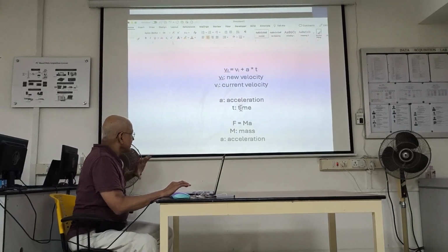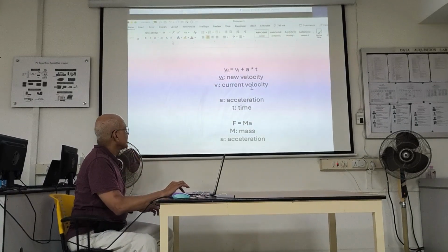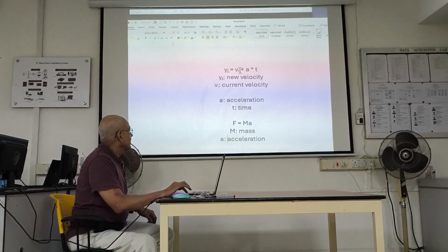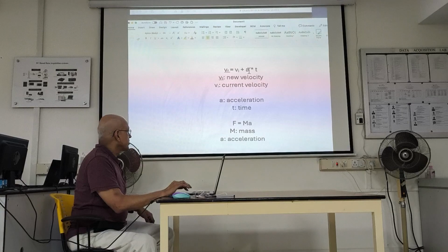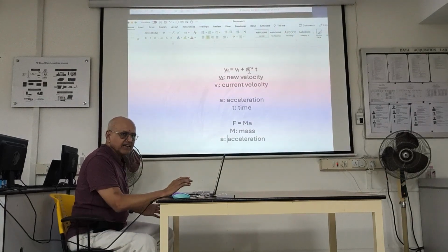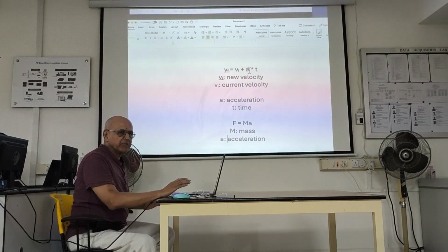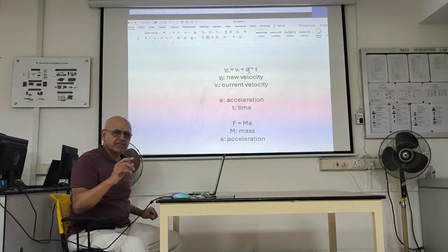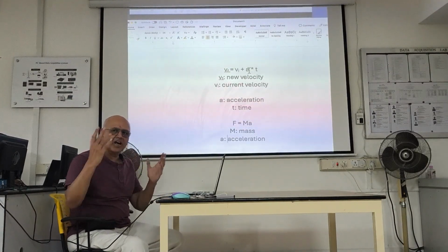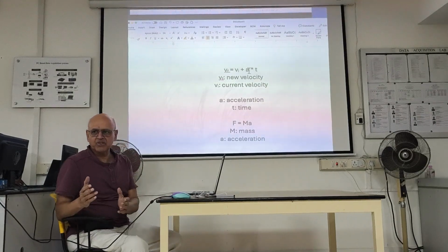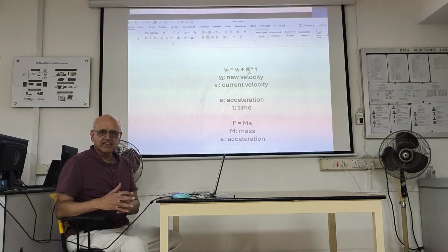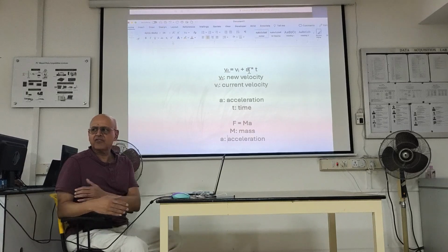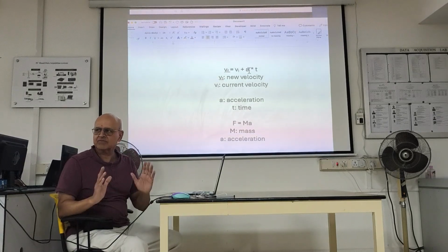However, let's just argue this out theoretically. What would it take for velocities to change instantaneously? It would require an infinite acceleration, right? So that's what kinematic models assume. They assume the acceleration is infinite. Or in practice, they say it's so large that we don't have to worry about the dynamics effects. So that's the approximation people often make in the real world.